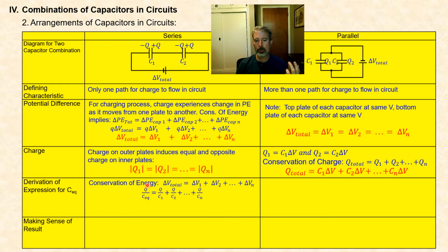And remember, the charge Q on that capacitor, what we're saying above, is the same as the charge on any individual capacitor. So do you see where this comes from? The charge on the single capacitor replacing the combination, divided by the equivalent capacitance of that single capacitor, must equal the sum of these terms when we take out the common factor of Q. This is the expression we get for the equivalent capacitance, and we write it as a reciprocal. For a combination of two capacitors, you can solve this for C equivalent as the product of your two capacitances divided by the sum of the two.